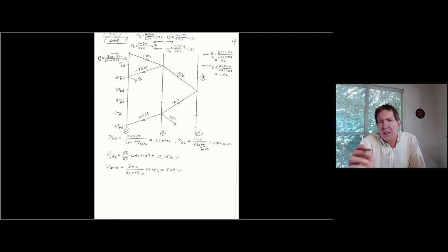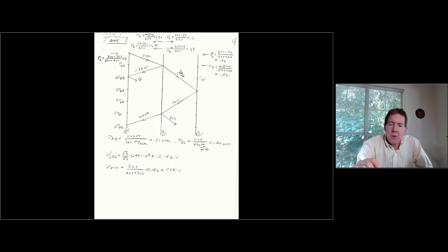And so you can take this into account in your diagram, where these dashed lines have to account for the fact that we have different speeds on the overhead versus the underground. I don't have the dashed line shown here in this case. So you've got the time for going down the overhead of 0.51 microseconds. The time going down the cable is going to be 1.02 microseconds. When you add both these numbers together, you get the total travel time going from the far left side to the right.